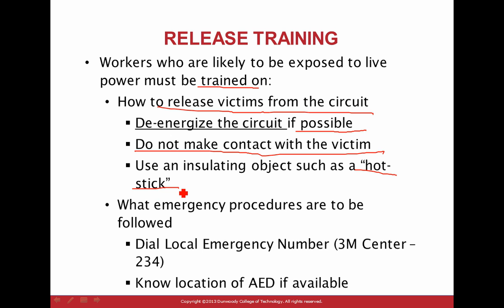Insulating objects, hot sticks. Or if you're in construction and somebody got electrocuted and you want to remove them, look for the closest non-wet wood piece of equipment. Don't bang them on their head, just slowly push them away. If you can't find how to shut down that piece of equipment, which you should, if you have a debriefing before you start the work, you identify how to shut down the system. But if you didn't, and nobody told you, and the guy's sitting on a circuit of 120 or 240 and shaking, use the closest wood piece of equipment and slowly push him away.